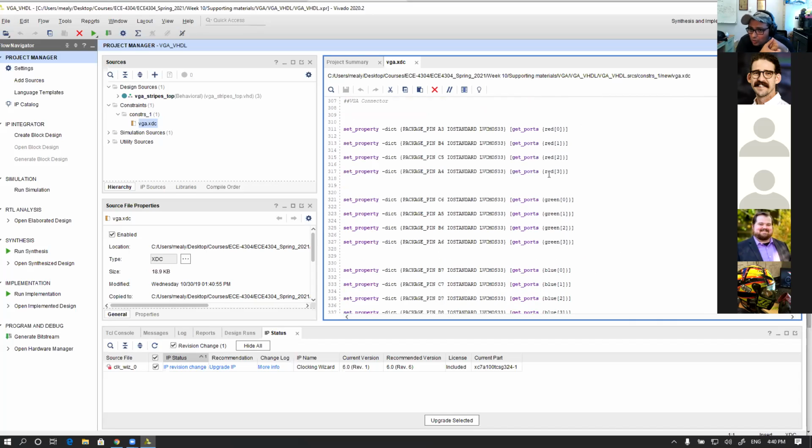In the VGA, it depends on the ADC. So you actually have a digital to analog converter, do you know that, right? Because we are talking to an analog interface. In hardware design there is something called digital to analog co-simulation, where I simulate the analog while pushing data from the digital. That is called co-sim. We are not doing this here because we need a specific license for ModelSim, and we are using the education version, which only allows us to simulate digitally, not analog.